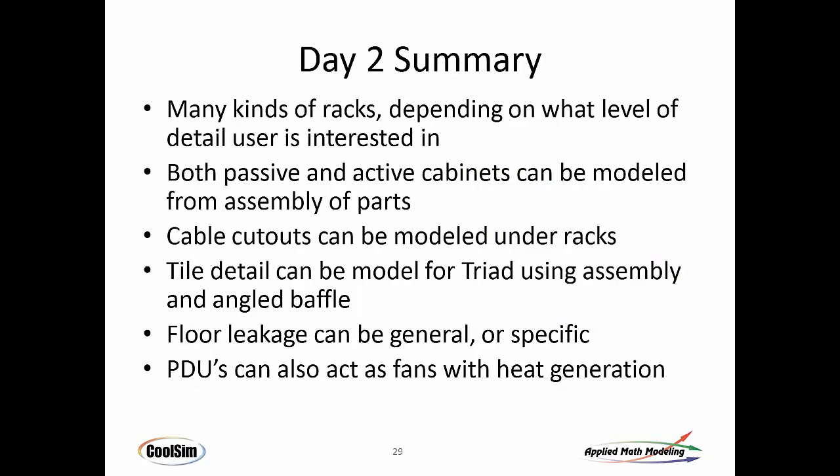So I guess the point is there's a lot of different kinds of racks. It does depend what kind of level of detail you want to get into. I would recommend average watts per rack, that each rack has its own level of wattage. Leave them on the floor at first until you get the model run and see what's going on, see where your big airflows are, see what the balance in the room is, things like that. You can model both passive and active cabinets. You can generally build them as structures.